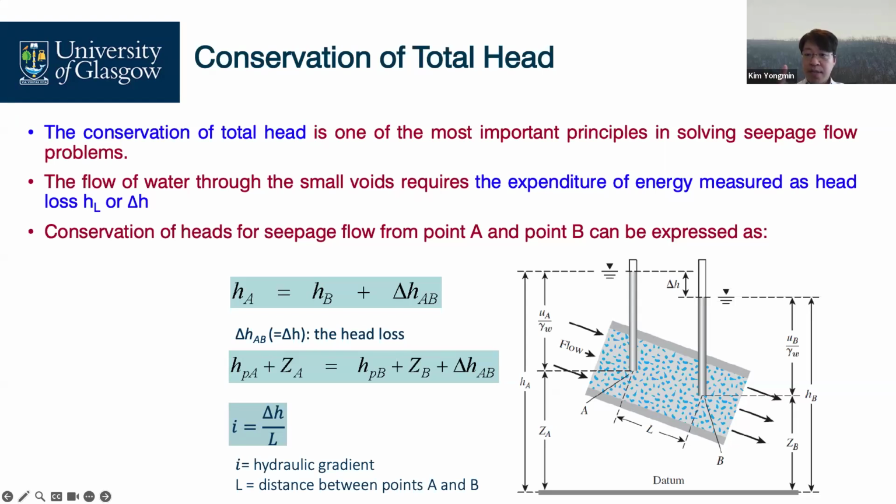We have one more thing I want to introduce to you, which is the i. This is the hydraulic gradient, which can be expressed in a non-dimensional form: head loss along a certain length of the soil body.